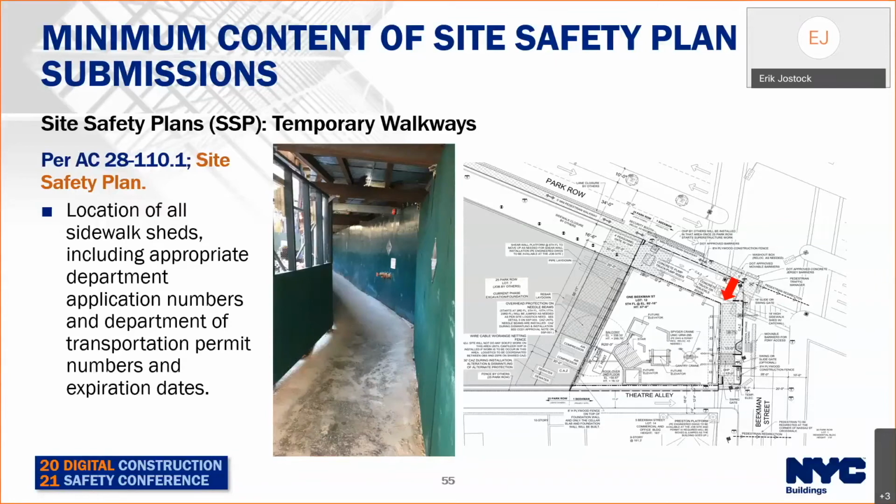And 3, enclosed along the side facing the street with a wire screen comprised of not less than number 18 gauge wire mesh or equivalent synthetic netting with openings in the wire or synthetic mesh no larger than ½ inch, or where special hazards exist, protected in accordance with section 3307.4.7.